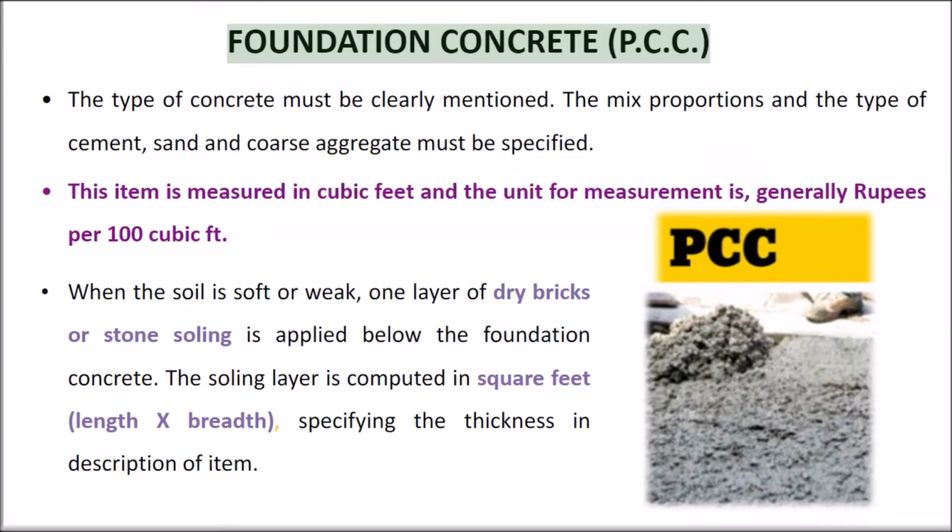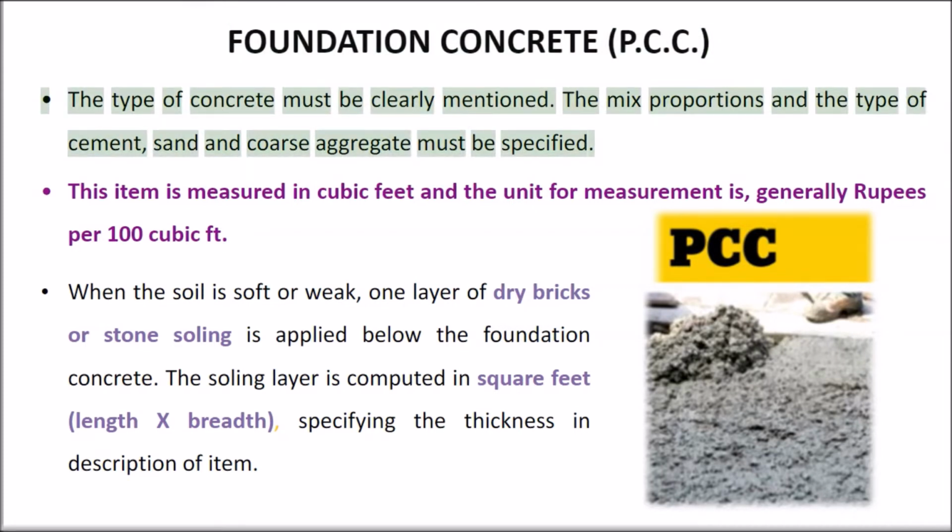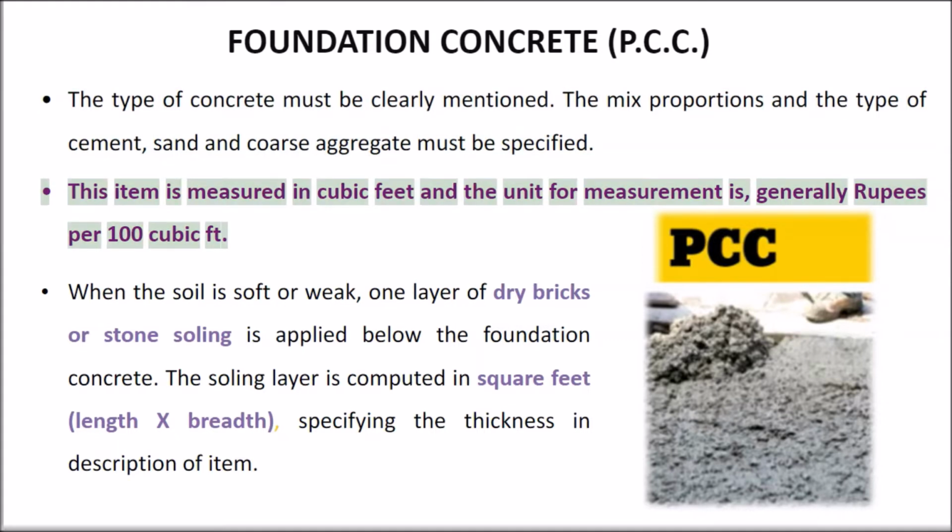Foundation concrete, PCC. The type of concrete must be clearly mentioned. The mix proportions and the type of cement, sand, and coarse aggregate must be specified. This item is measured in cubic feet and the unit for measurement is generally rupees per 100 cubic feet.